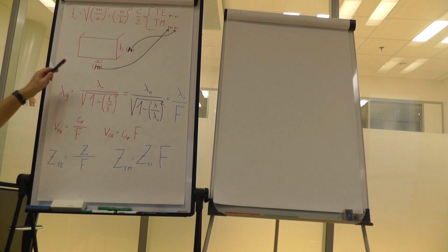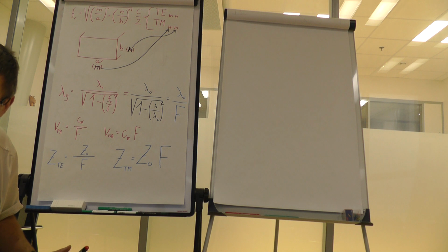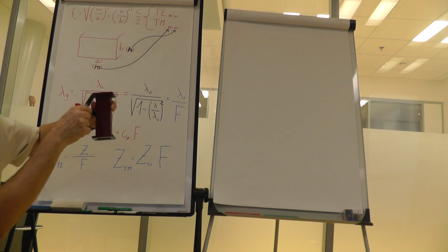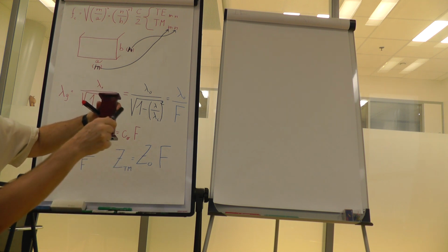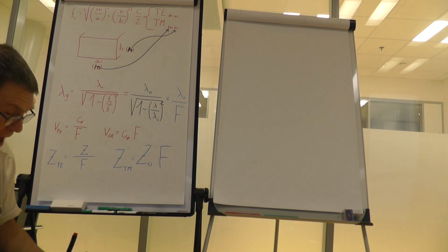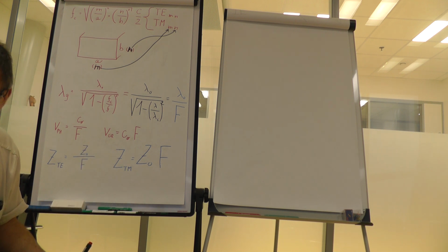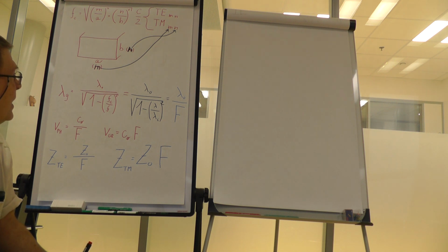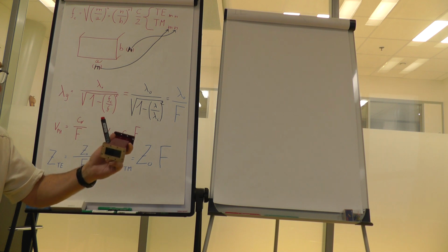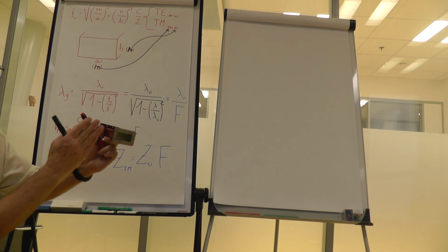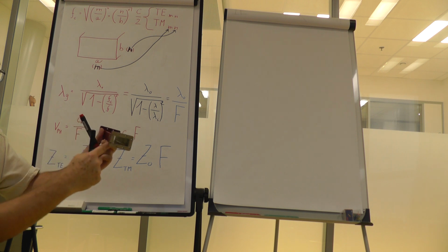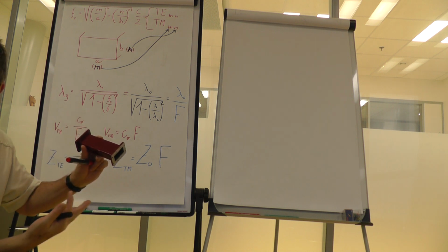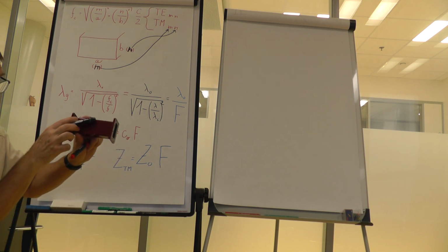Now, as we had the chart before and in the last lecture, we can imagine the wave propagating like bouncing in the waveguide from one wall to the other, with everything connected through the Pythagoras equation, so that for example, the wavelength that is observed along the enclosure of the waveguide is longer, because that's a projection of the wavelength of the original wave inside, which travels a bit tilted.